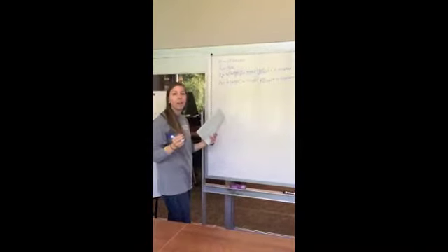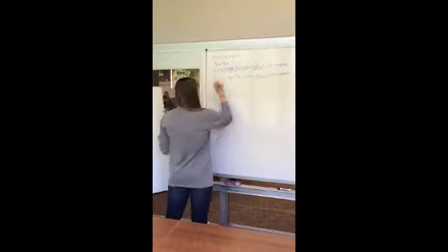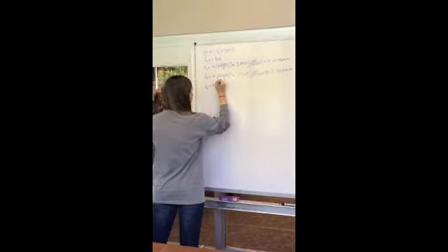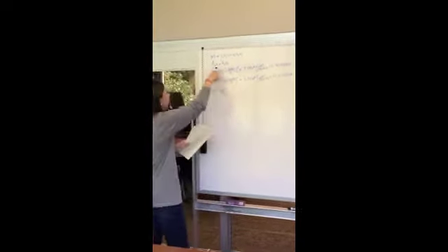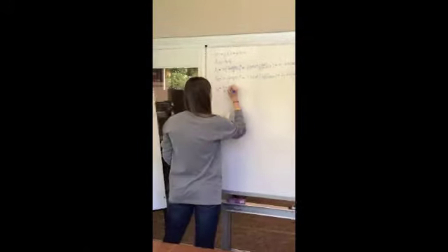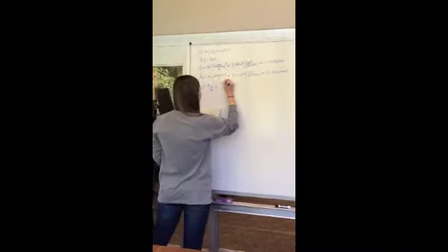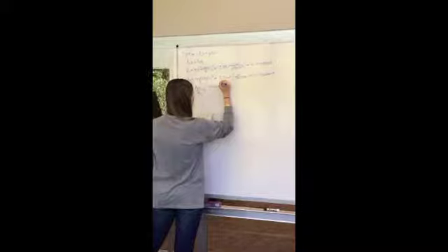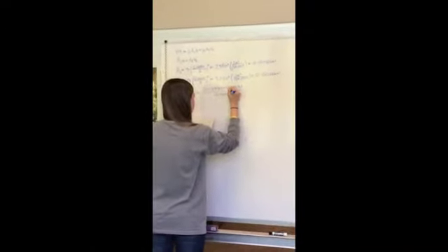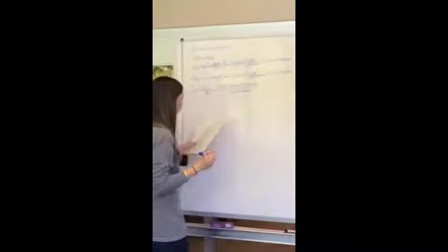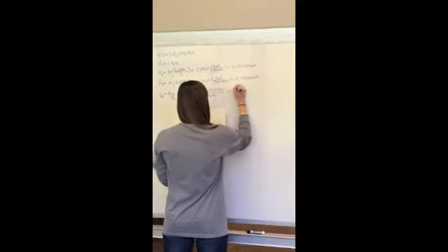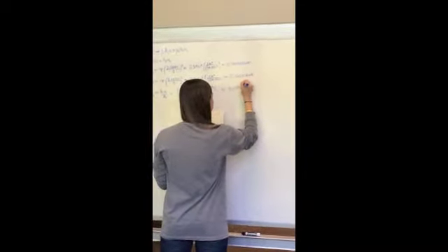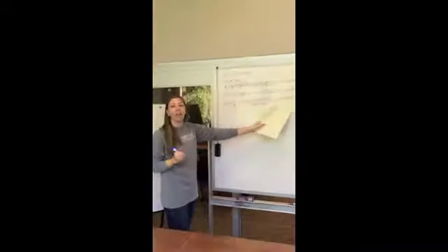From this, we can find velocity 2, the velocity of the outlet. And this comes from up here, our mass balance equation. Plugging in our areas that we found, if you plug this into the calculator, you will get 4.075 meters per second. And this is our outlet velocity.